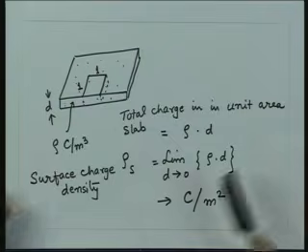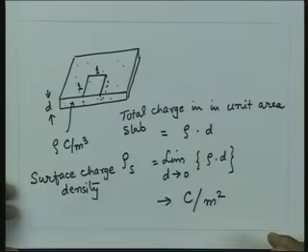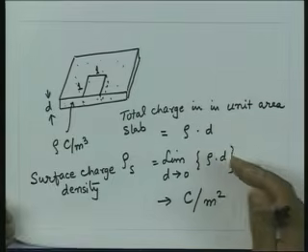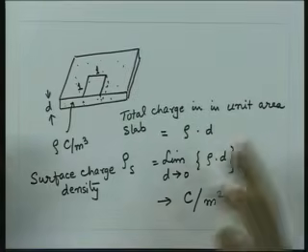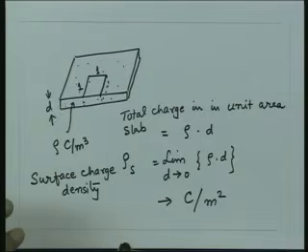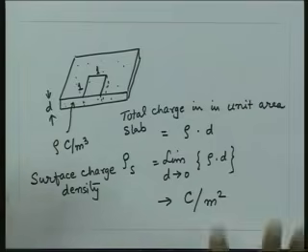So, later on we will see that in situations like conducting boundaries, where the conductivity becomes infinite, you might get the volume charge density which will be infinite, and these charges truly will be confined to the surface, and that time this concept of surface charge density will be useful. So, at the moment, without getting into which media will give me surface charge density, we can say principally we may have charges distributed truly on the surface within a 0 thickness, and that charge density we will call as a surface charge density. The similar thing we can do for the current also.